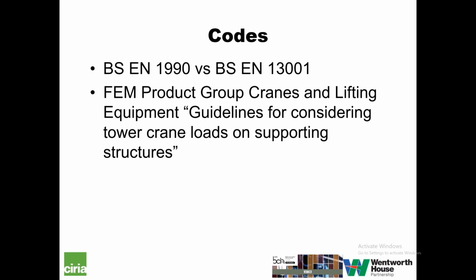And this in fact results in different load factors for the storm on the front load case, which is an unusual load case, almost an accidental load case, and the other general load cases. It is therefore within the spirit of the Eurocodes, whose aim is to get a consistent factor of safety.